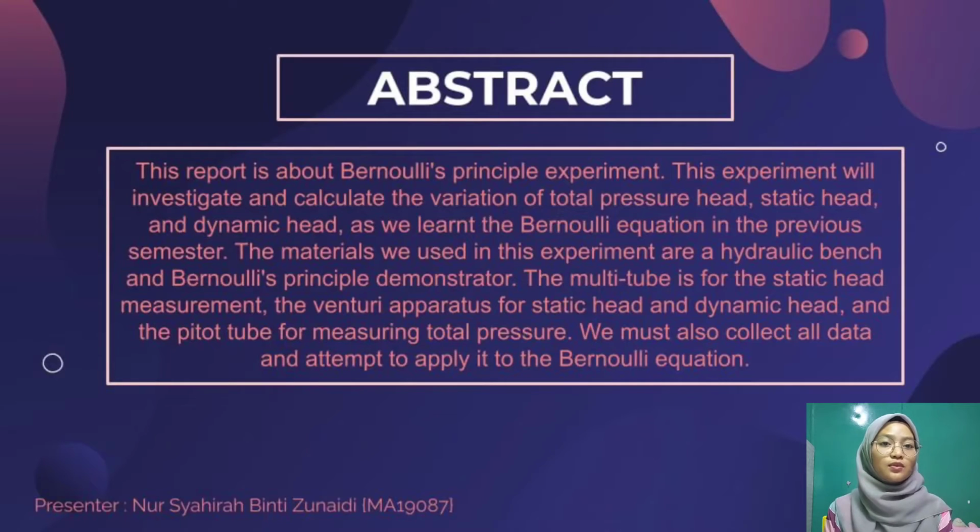The materials we use in this experiment are a hydraulic bench and a Bernoulli principle demonstrator. The multi-tube is for the static head measurement, the venturi apparatus for static head and dynamic head, and the pitot tube for measuring total pressure. We must also collect all data and attempt to apply it to the Bernoulli equation.